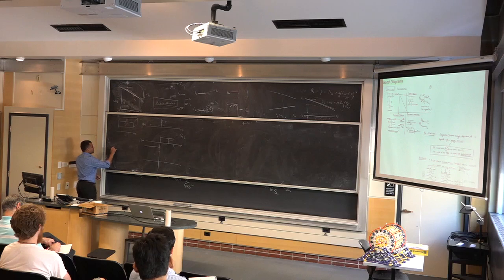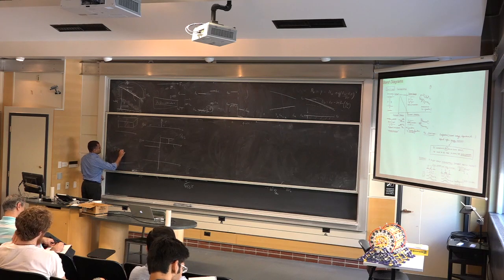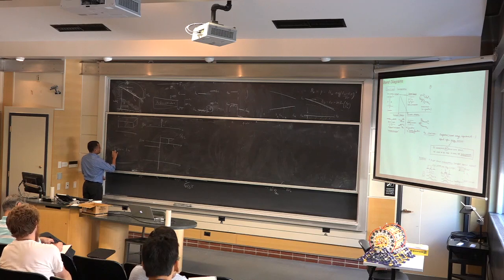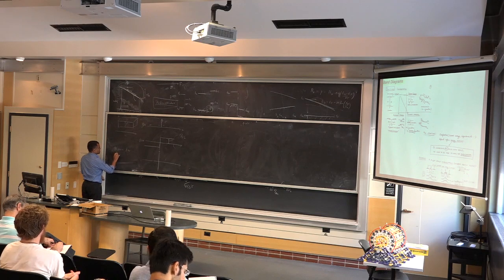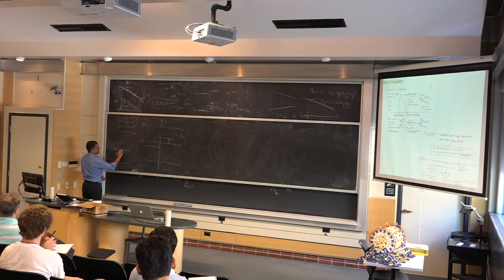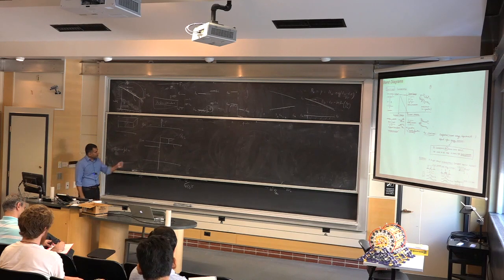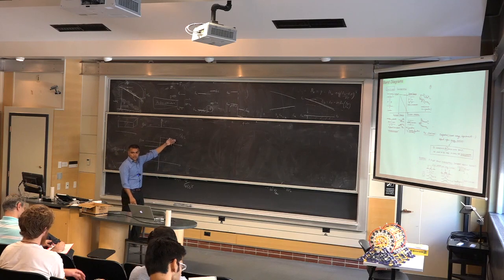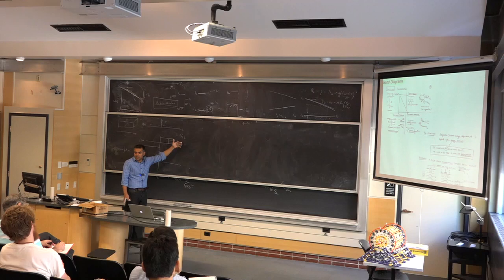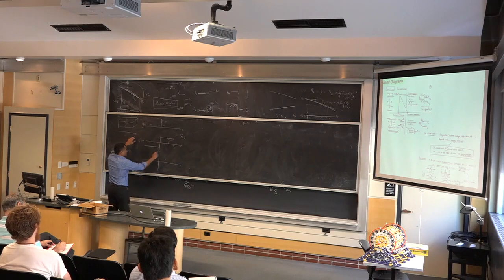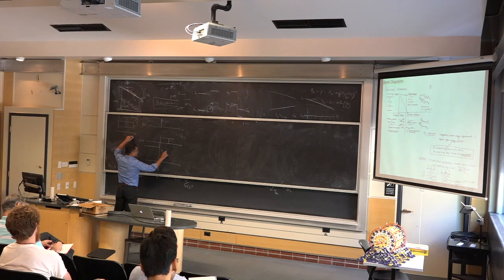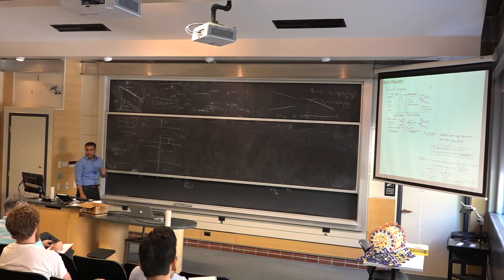I think you know that the gradient of potential is equal to the electric field, which in one dimension is just d over dx. And so the potential is really an integral of the electric field, with a negative sign. So you can pictorially integrate this. The field is a constant. What's the integral of a constant? It's a linear function. So that much you know already. And so if I were to plot the potential, in fact, I can go 2 steps and just plot the conduction band energy, and that will be minus electron charge times the potential. Conduction band as a function of space.